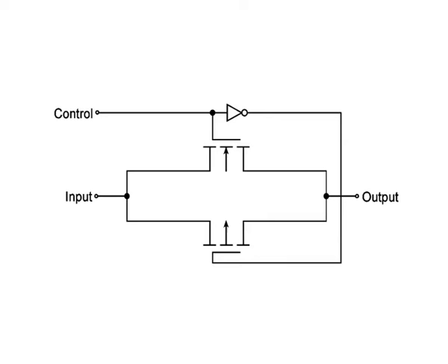Such behavior causes no problem in static CMOS logic gates, where source terminals of all N channel MOSFETs are connected to ground and source terminals of all P channel MOSFETs are connected to VDD. This would cause a problem if a single N channel or P channel device were used as a switch.